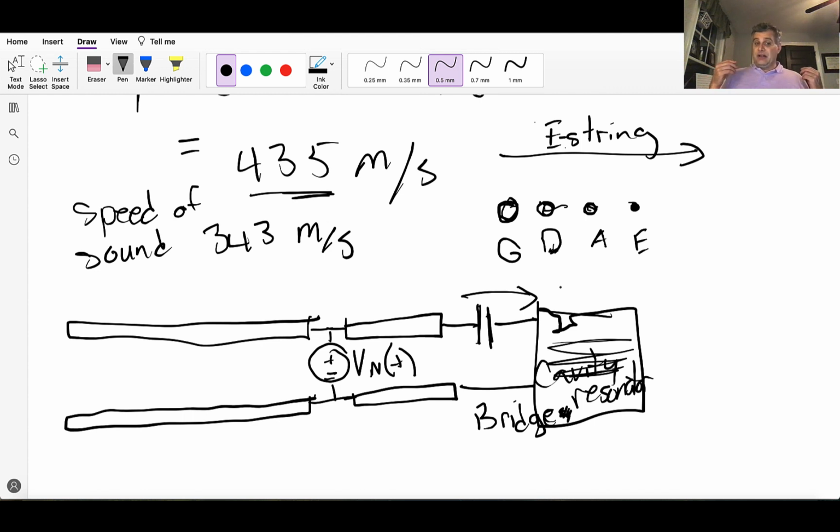Because it's not a simple TEM, transverse electromagnetic structure, like a transmission line is, a cavity resonator has lots of different modes. The fundamental, or the cutoff, is the lowest possible frequency that it can excite. As we learned in classes, a rectangular waveguide with the ends sealed up is a nice rectangular cavity resonator. It has very predictable modes that you can excite as the frequency goes up for a particular geometrical structure. The bigger the structure, the more modes it has, the bigger with respect to a wavelength.